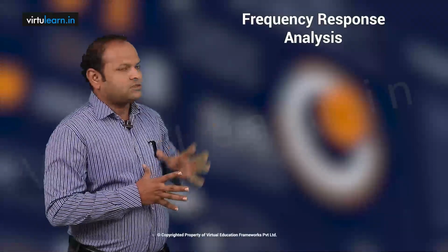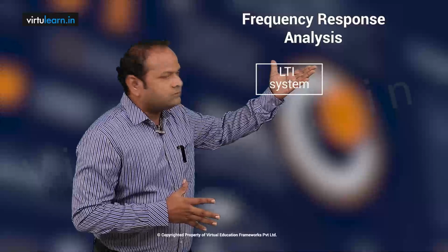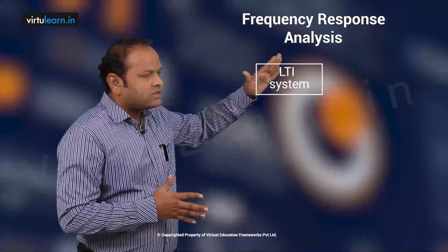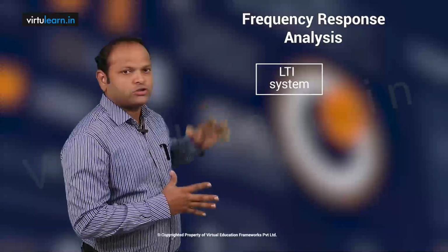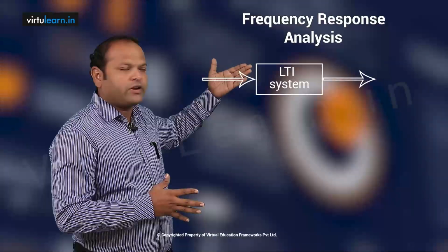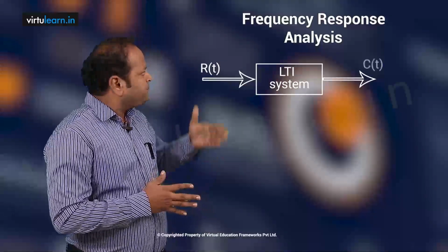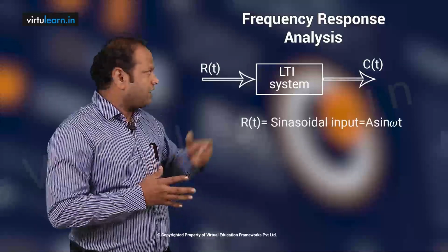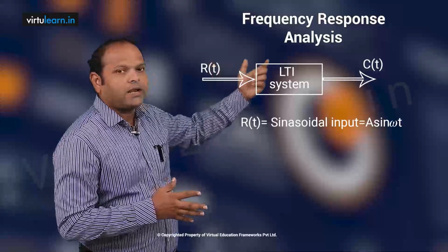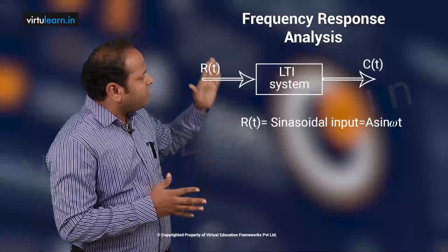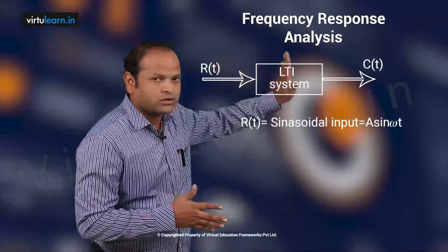What do you mean by frequency response analysis? Let us take this system, and this is a system, LTI system, linear time invariant system. And for this system, I am connecting the input and the output. So input is R of t and output is C of t. Let us say this input is sinusoidal input. For example, R of t is equal to A sin omega t, where omega is a frequency, t is a time function. Then this sinusoidal input is connected to the system.